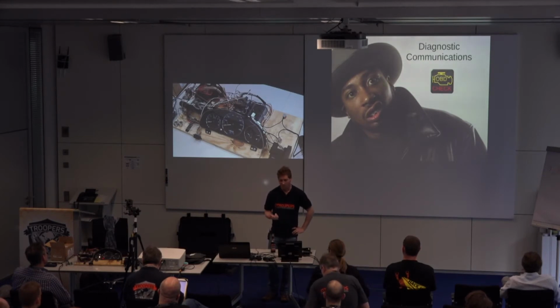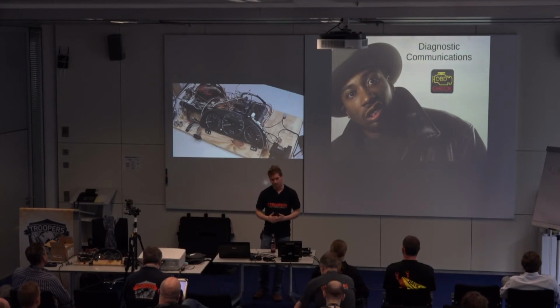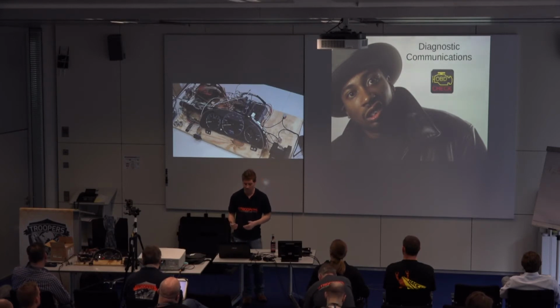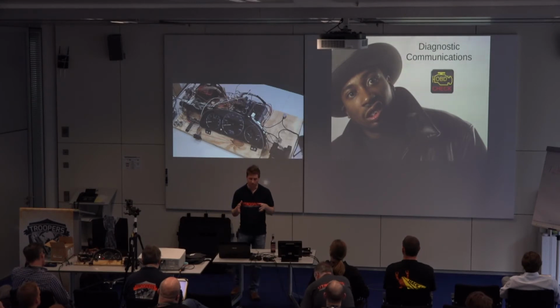That's what the car is actually reacting to. This is more, if you're familiar with networking, like SNMP. You make a query to it, and SNMP wraps up some data and sends it to you. It's kind of a read-only portion. You can write to it. It does have some flash capabilities, but for the most part, it's just a query system. But they're connected to the exact same two wires. The protocol is a little more complicated than CAN, but it runs on CAN. It's just a modified interpretation of CAN.